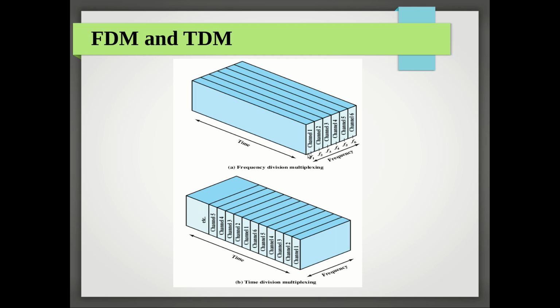Centered on this frequency, this much range of frequency is allotted to channel 1. Similarly, like that, here it is a division of 6 channels. You can think of more divisions also depending on the requirement, but there is no splitting of the time. So between a sender and a device, the whole subcarrier is allotted to a given communication without any disturbance. So that is the idea.